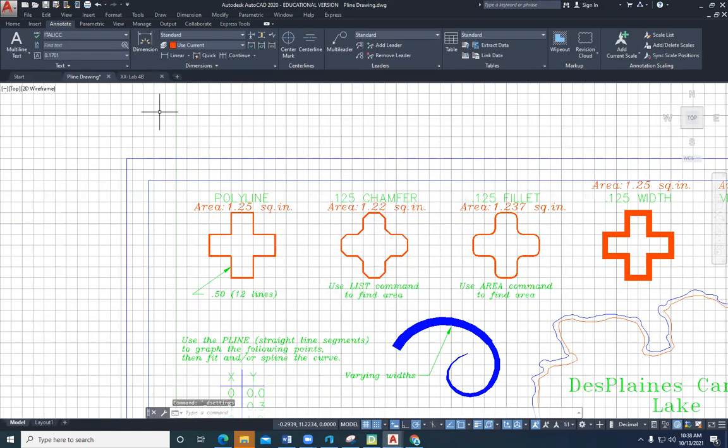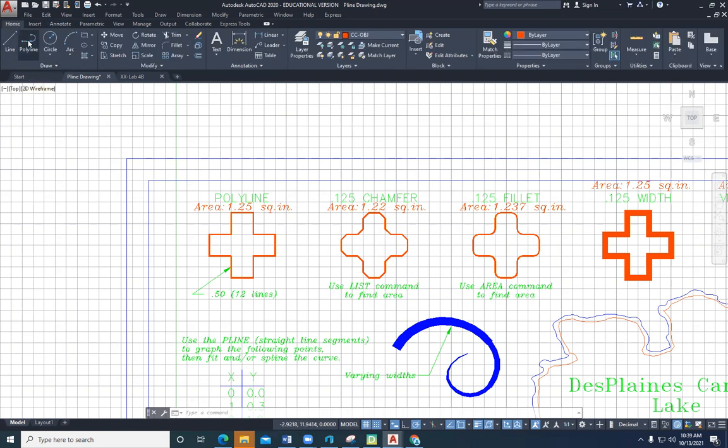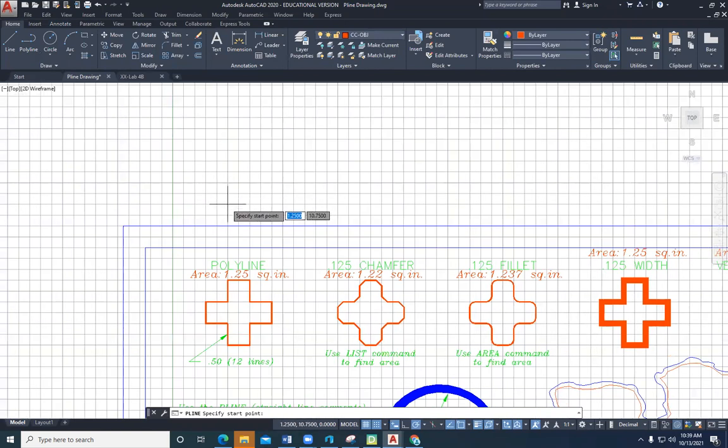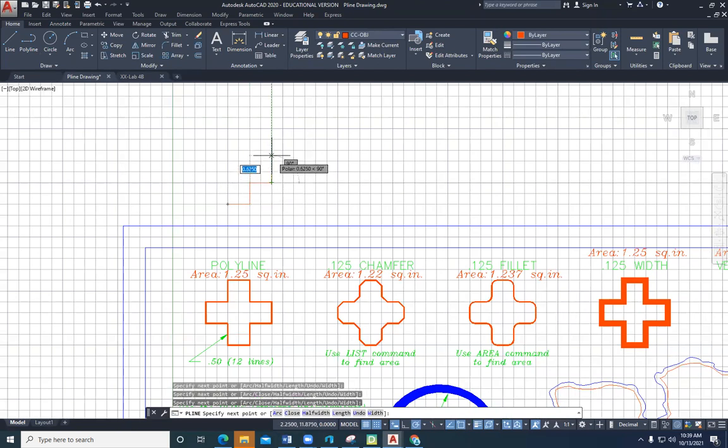And then on the home tab, we're going to create a polyline. So I'm going to switch over to the home tab, and here's the polyline command. Essentially, when we work with polylines, all we're doing for this exercise is creating these shapes. It looks like the line weight's a little bit light, does it not, Al? A little bit, yes. We'll say C for close.